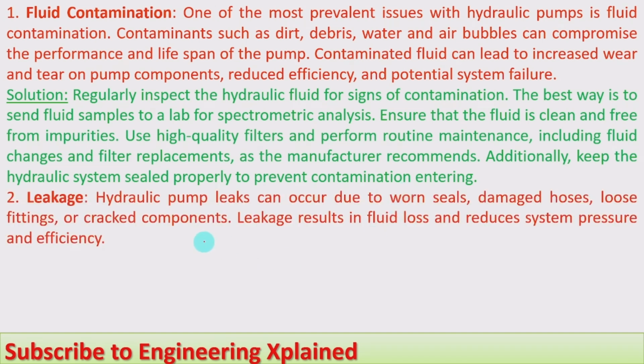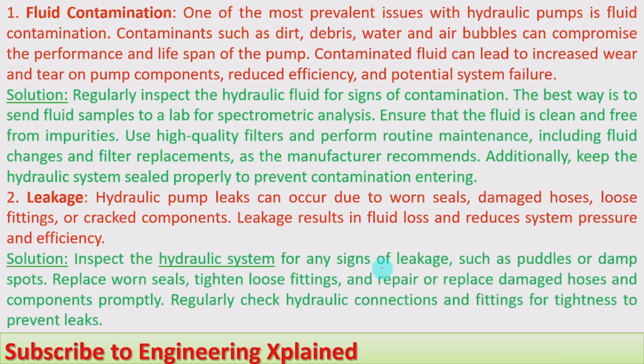The next one, leakage. Hydraulic pump leaks can occur due to worn seals, damaged hoses, loose fittings, or cracked components. Leakage results in fluid loss and reduces system pressure and efficiency.